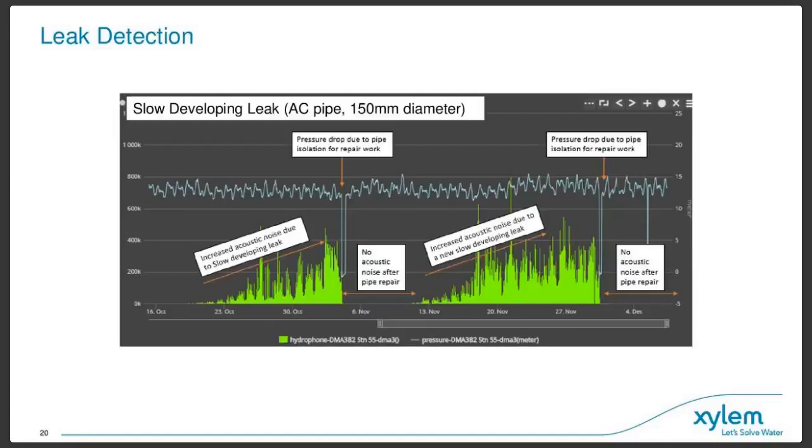leak. And then after that, there's a validation that sure, the leak has been detected, but then another leak appears to develop nearby because the hydraulic condition of the network has changed, and it becomes quite common to see other leaks appear around this time as well. And so again, you see this, and an alarm is raised as the trend rises up, and then again the leak is found, and then no noise validated after the repair.